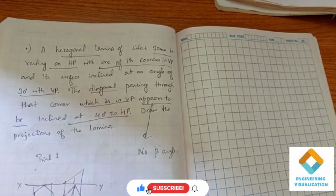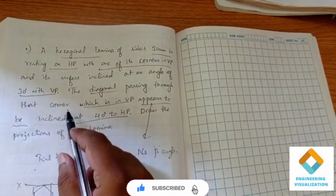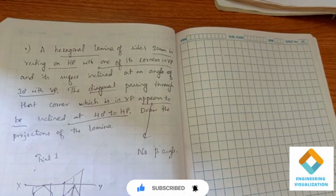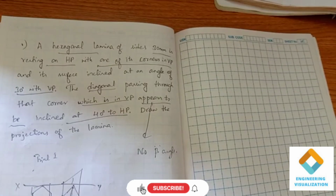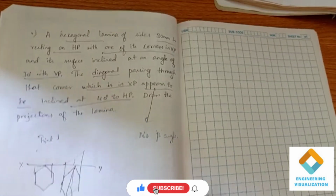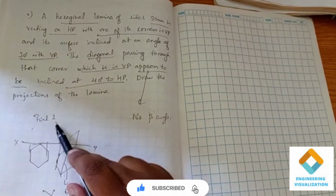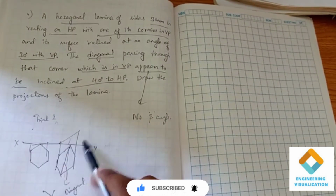So this diagonal is there in the HP plane. But the question is telling us that the diagonal passing through that corner which is in VP, so that means this diagonal has to be there in the VP plane. That means this trial is wrong. So in this problem we run the first trial, resting on the HP plane, corner touching the VP. So inclination we have mentioned.